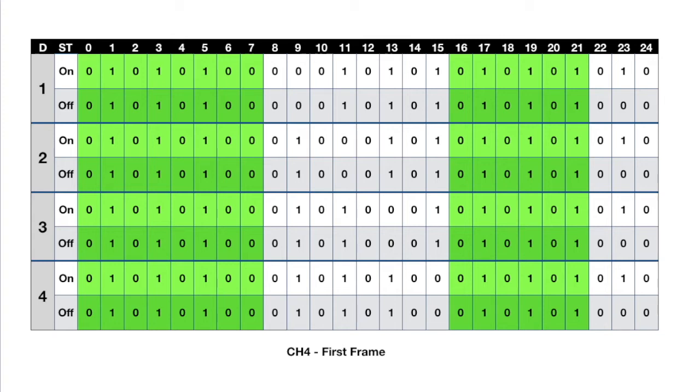16 to 21, we have no idea what they are, because they're always the same. And we know that bits 22 and 23 are the bits that control turning on and turning off the devices. I would guess that bits 16 to 21 are also device bits, and this is there for provisioning for more devices. So here I have 1, 2, 3, 4 devices, but I could have 5, 6, and 7 devices in total being controlled by these kinds of remote controls. So I'm assuming that from bit 8 to bit 21, but I'm not sure, these are device bits.